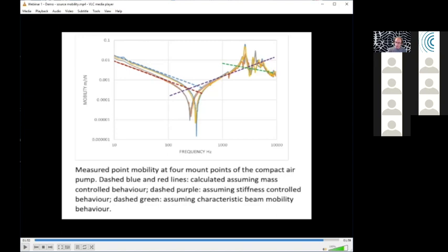So in this demo, we've taken a simple mass and made a slight modification to show that the structural dynamics of a seemingly complex piece of equipment can sometimes be approximated by a combination of masses, springs, and dampers, with consideration of these resonances at higher frequencies.